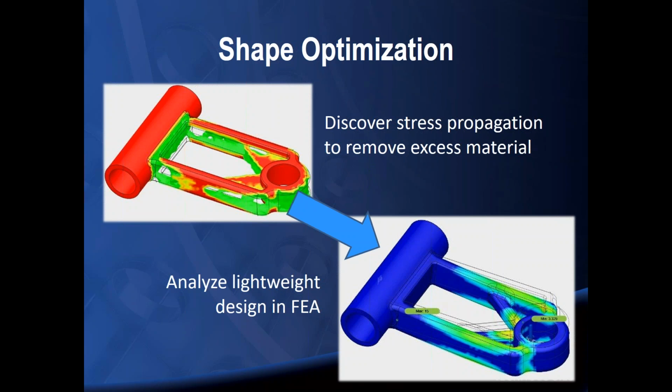to those components. And so shape optimization tends to be coupled along with some of these stress analyses where I can run shape optimization, see where I need to put some supports within my parts and then remove excess material. But then we can also move from there over into the stress analysis to do a final run on our components to make sure that, sure enough, they will withstand whatever type of simulation it is that we're trying to run here. In this particular example, we're applying a torsion load to an arm for a suspension and seeing how that ends up reacting.